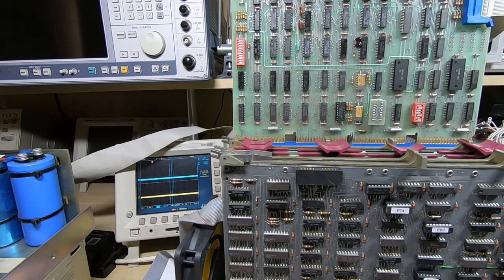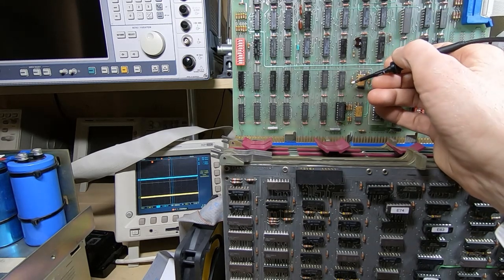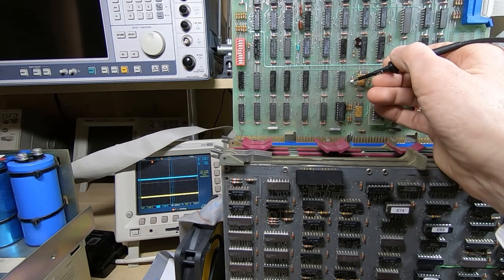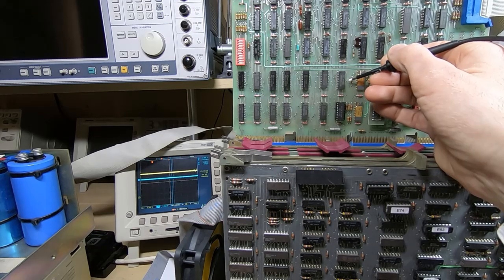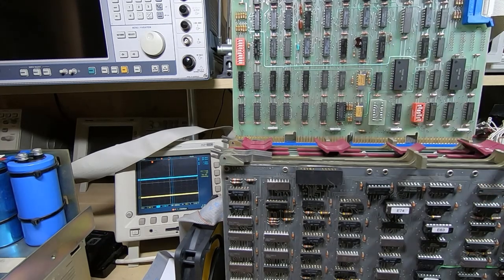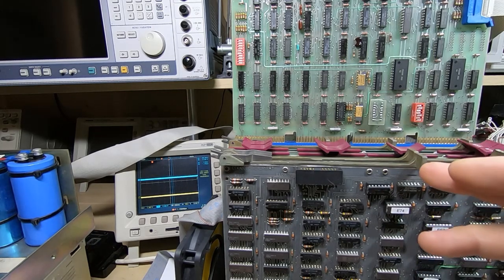So we'll try another value. I'll reset it first because we've now started a function, so I need to reset that. So I'll do a reset, and now I'm going to send a value of 5, and that will set the second bit high and the other 2 still low. So I've sent a value of 5. The first one should be low, the next one should be high, and the last one should be low. Okay, so I'll go through the other combinations, and then if they're okay, we'll come back and continue.